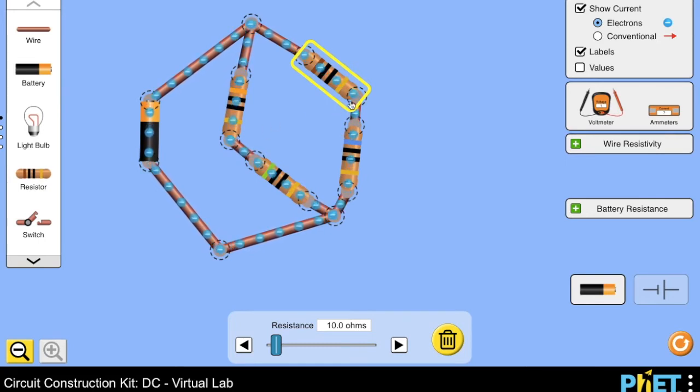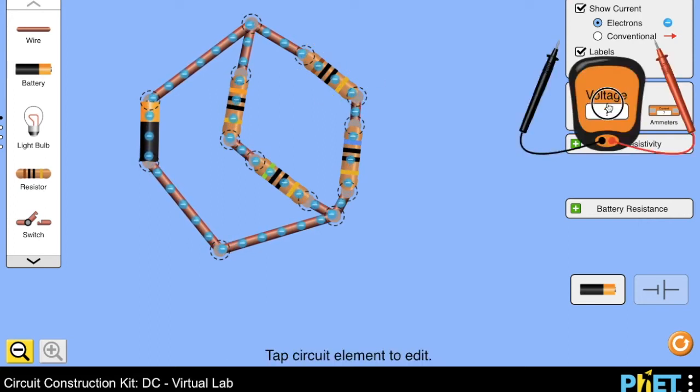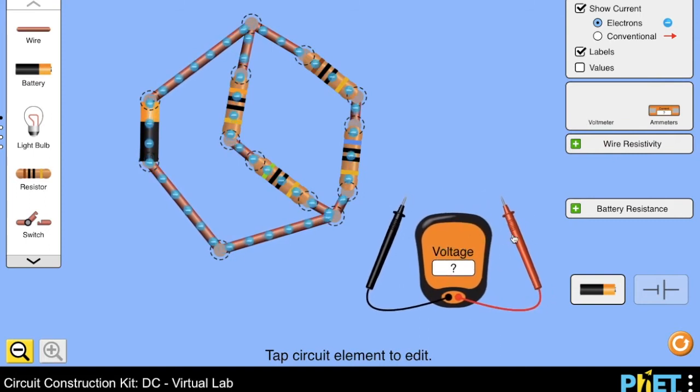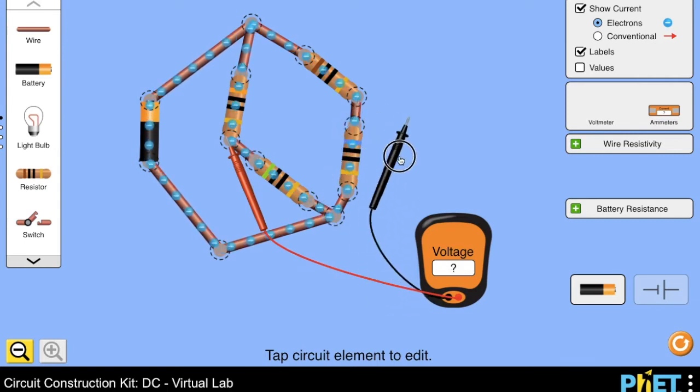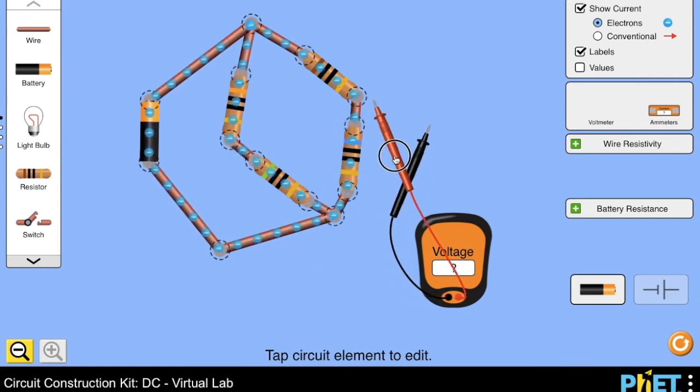The resistance which we are going to vary in order to render these two bridges balanced. And like we have said before, these two bridges are balanced when the voltage at that point is equal to the voltage at the opposite point. Therefore, the potential difference between them would be equal to 0, and there is no current flowing between them. So for that matter, we are going to bring that voltmeter and connect it between these two bridges. We are reading a negative value, meaning that we need to switch the plugs.